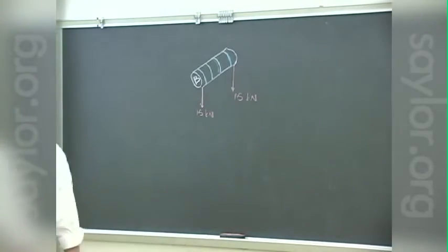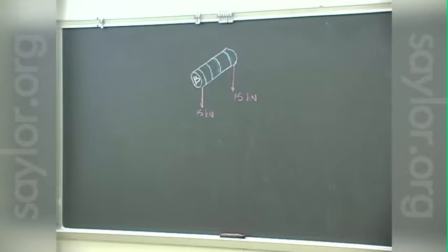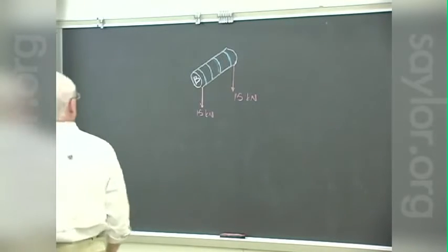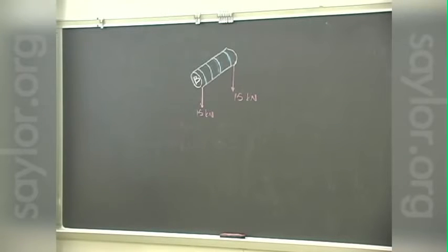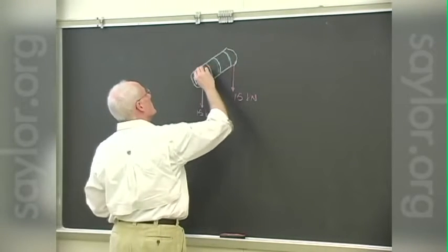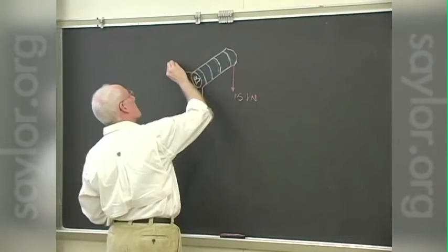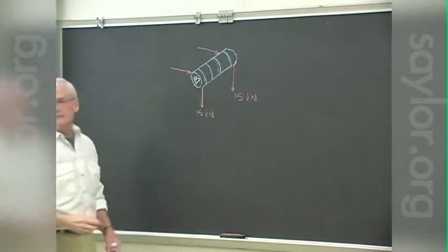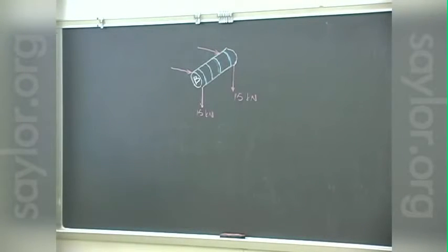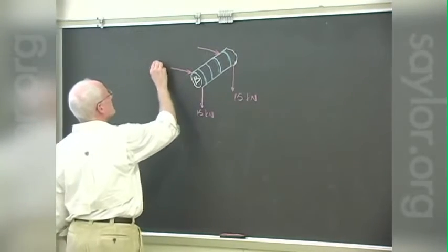By symmetry, we assume half of the 30 kilonewton load is on each one of those. And then the part AB comes in, that's this U bracket at the end of that, so that's the 2 pieces. And the piece itself is in compression. What was the load in that? 40 kilonewtons, right? So there's 20 kilonewtons on each of these.